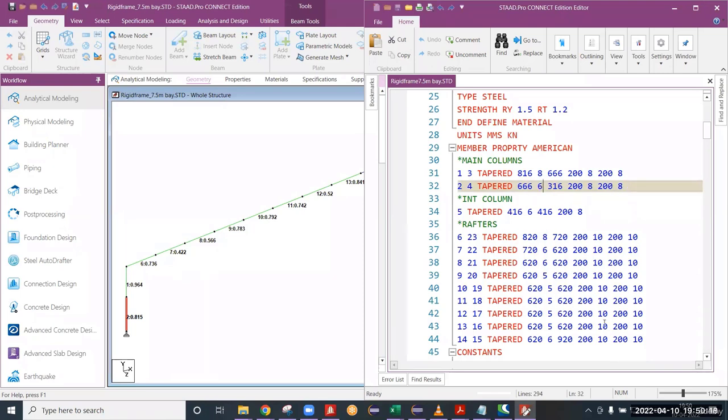Instead of that, you can try to reduce the thickness of the web here. Here also you can reduce the thickness because it is critical in combined flexure and shear, not only in shear. So I'll try to reduce the shear only, because if you decrease the thickness, it may fail here, and this causes more weight. That is why I have reduced it from 8 to 6. So just keep it like that.